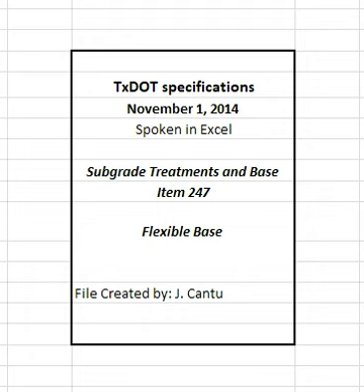2.1.2 Material types. Do not use fillers or binders unless approved. Furnish the type specified on the plans in accordance with the following. 2.1.2.1 Type A crushed stone produced and graded from oversized quarried aggregate that originates from a single, naturally occurring source. Do not use gravel or multiple sources.